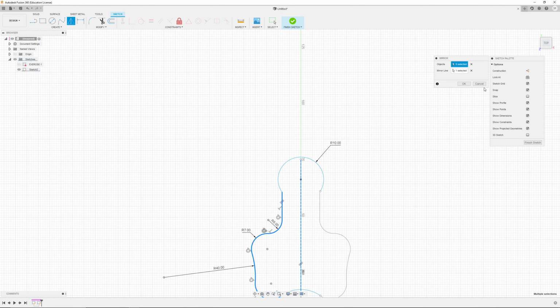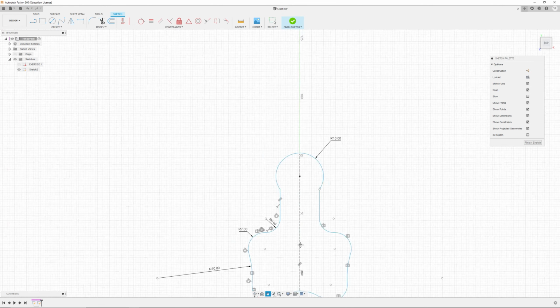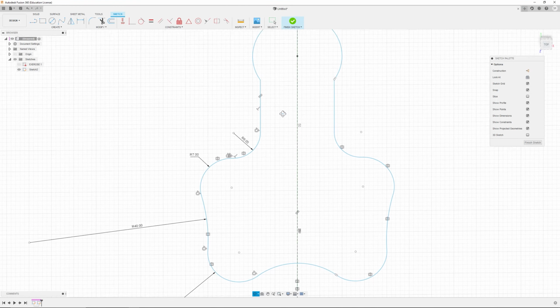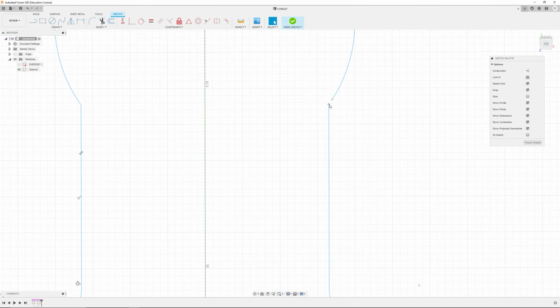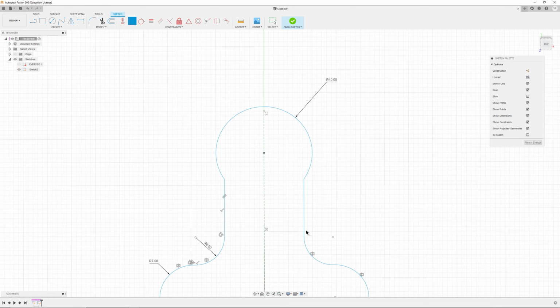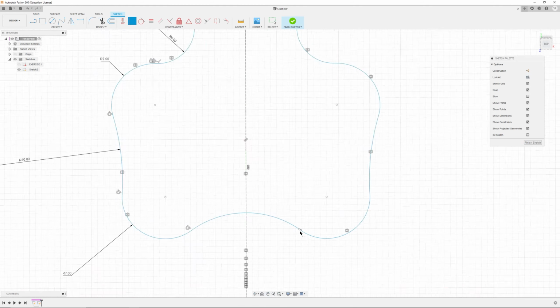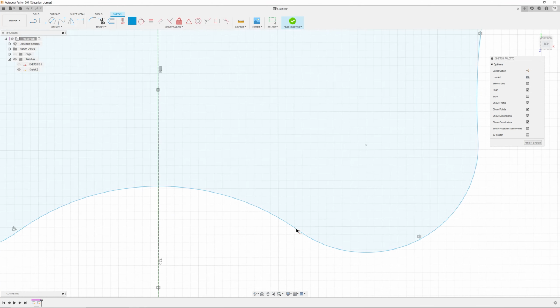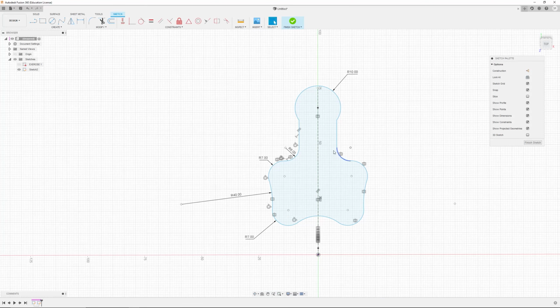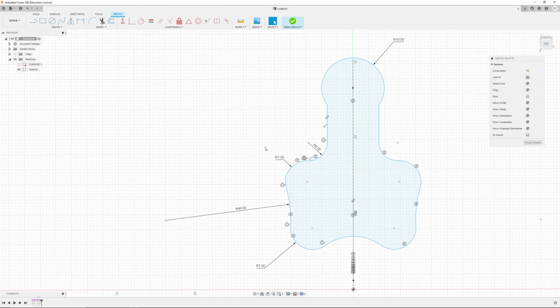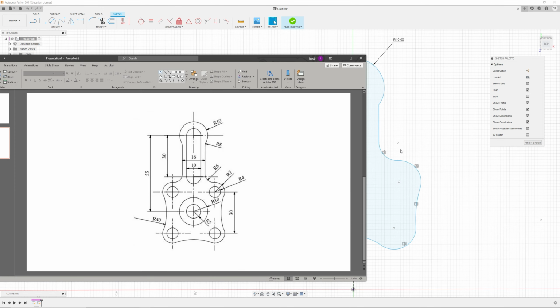And that's it. So I hit OK. So now we have lines on both sides there that are nice and defined. And I can take those 2 points, make those coincident, and take those 2 points, make them coincident. There we go. And now if you notice, as soon as I did that, it's shaded in the inside. That just implies that it is fully enclosed.